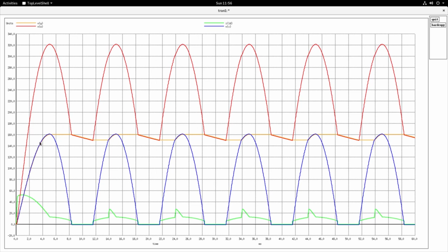See that after it has followed the input and then come to the 50% mark, Vm by 2, it then holds there till the input voltage comes below the Vm by 2 point, when the rectifier diodes stop operating and the capacitor is discharging into the load. Each capacitor discharges into the load till again the input comes up and then crosses over here, the rectifier diode comes into operation, and then you have the output following the input.